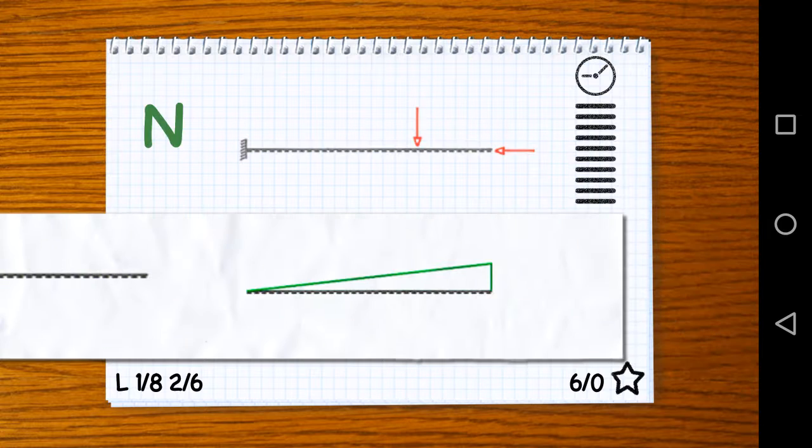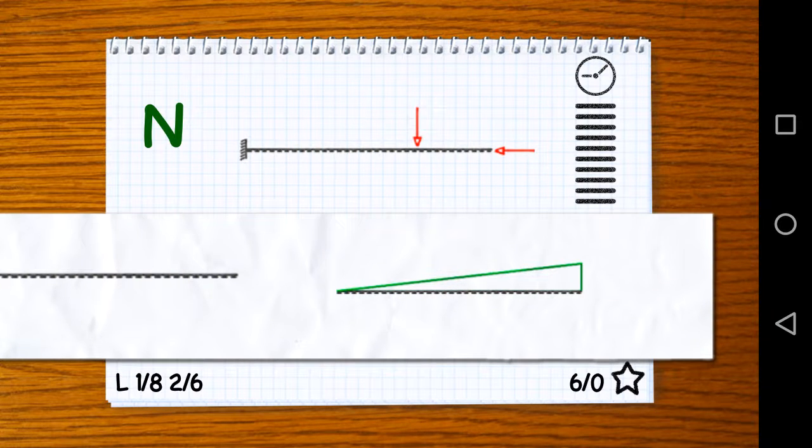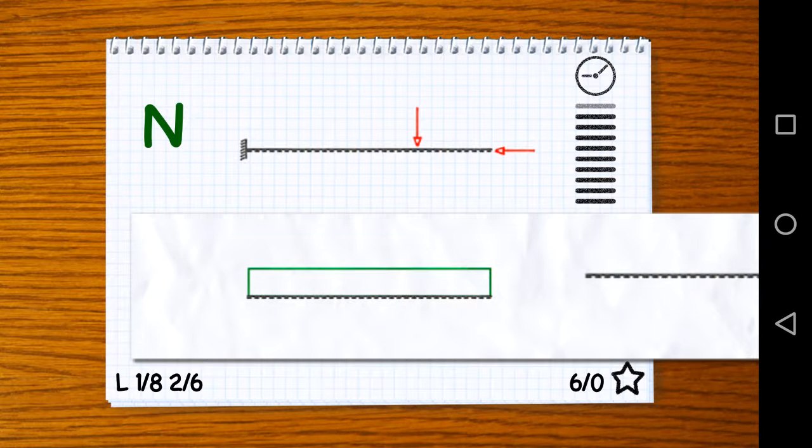So here's the answer. Normal forces are just about compression or tension. So the force here that's perpendicular to the beam is irrelevant for normal forces. The only one that's relevant is the one that's horizontal and pointing to the right. And what is that force doing to the beam? That force is putting the beam under compression. So we're going to have a negative normal force here, a negative normal distribution. Like I said again, the interrupted lines down there indicate the positive side. So it's not like in math where positive is above and negative is below. Here it's basically the opposite.